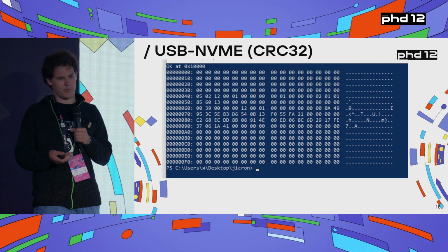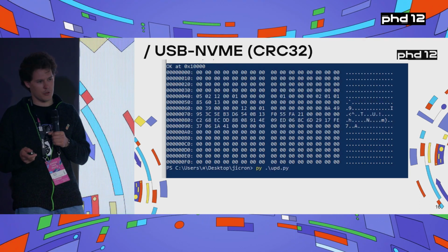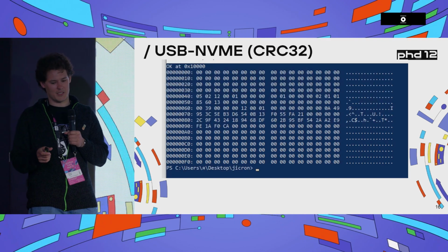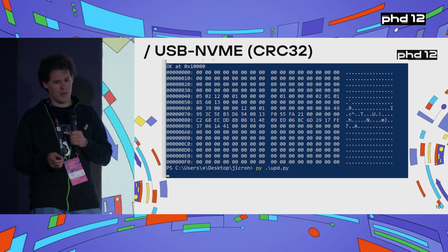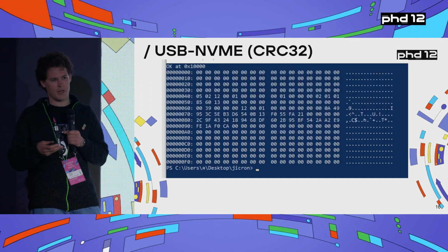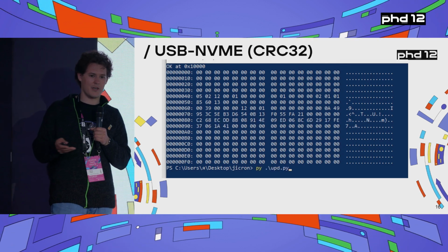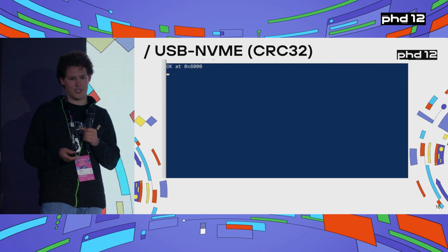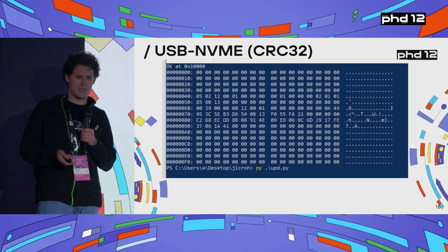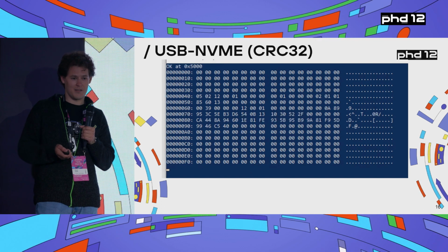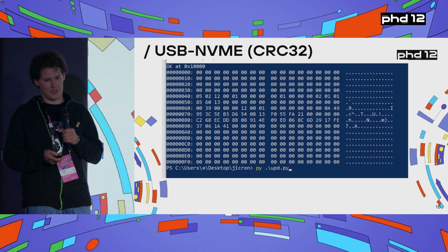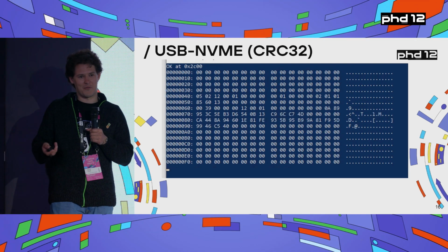It can be 1, 2, 3, and as we're trying to update the firmware, we tried to read the RAM, and we discovered there were some minor changes happening every time a new block of firmware was being dispatched. So we decide, okay, must be 32-bit calculation happening there. And then another colleague of ours said that in this utility, he actually found a bit unusual polynomial for CRC calculation.